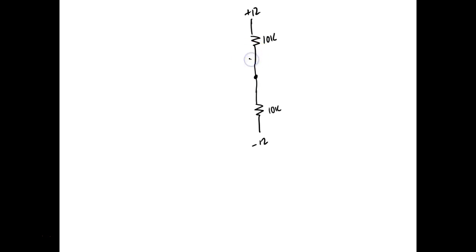Well, if these two diodes right here are matched, so here's 0 volts relative to the diode, right? You understand this. Now, this is 0 volts relative to the diode. So what that means is this is 0 volts. This has to be minus 0.7. This right here has to be plus 0.7, which puts the transistors right at what?